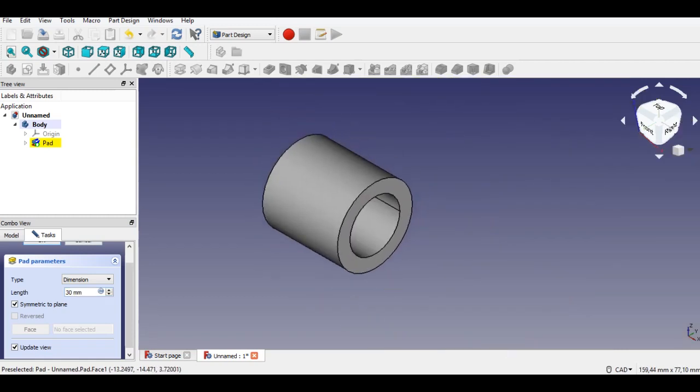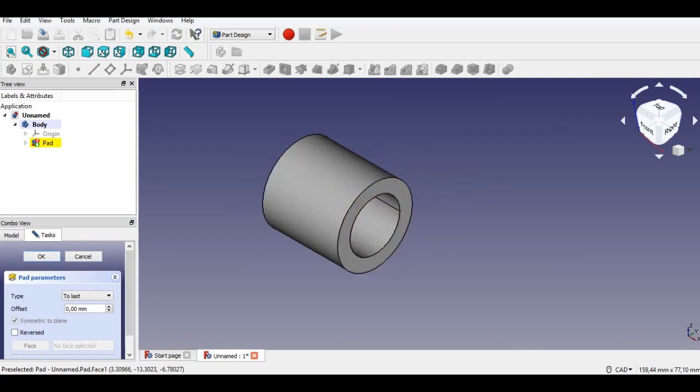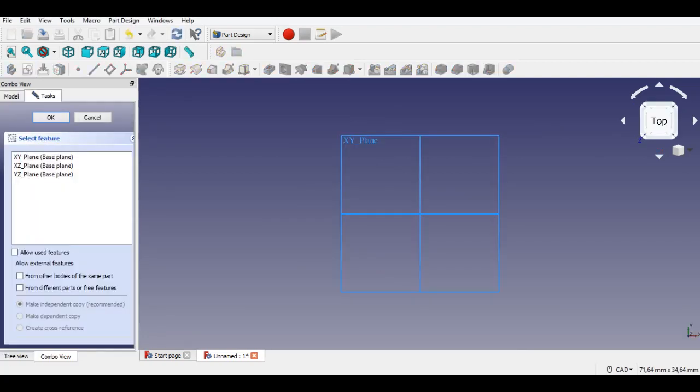We select the YZ plane after clicking the sketch command. We will create the part 3 sketch with constraints. First we click the multi-line command and start creating a geometry to revolve in the Part Design environment.